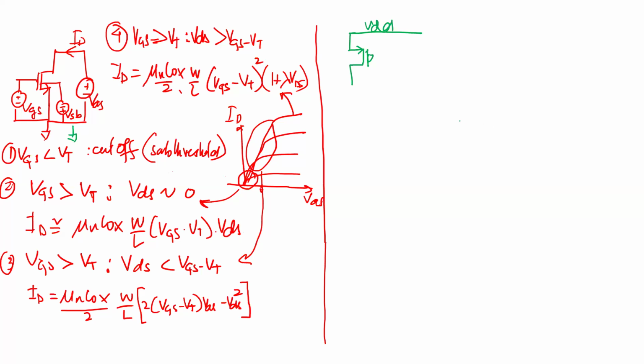All right. So I think the bubble one is probably better, but in analog, you use the arrow one because it tells you which direction the current is flowing. Okay. So now here, the gate to source voltage is negative, right? That's VGS or VSG. If you want to write it as a positive quantity, then VSG. But your voltage is, this is positive and that's negative. So your gate to source voltage is a negative voltage, or a source to gate voltage is positive.